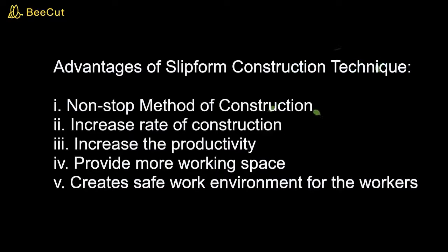There are a few advantages of the slip form construction technique. First, it is a non-stop method of construction. Second, it can increase the rate of construction. Third, it can increase the productivity. Fourth, it provides more working space. And fifth, it creates a safe work environment for the workers.